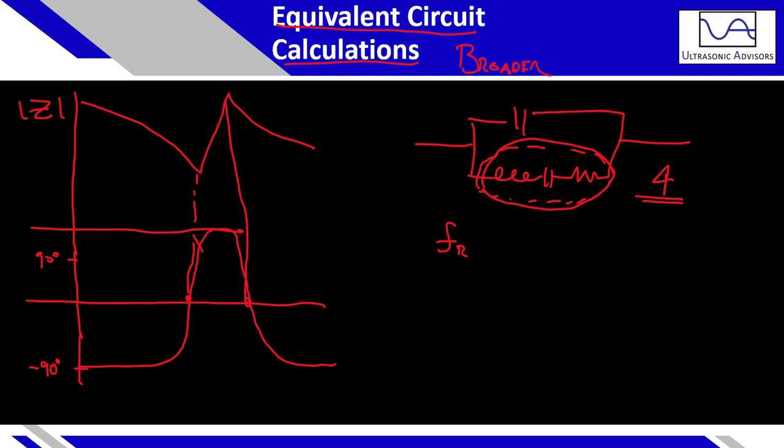So if we have the maximum power dissipation, which basically means there is no impedance, this inductor and capacitor are in resonance, therefore they're not providing any opposition to current flow, and thus all of the current draw will be completed over the resistor, thus causing maximum power dissipation. This is actually the frequency of maximum real admittance.